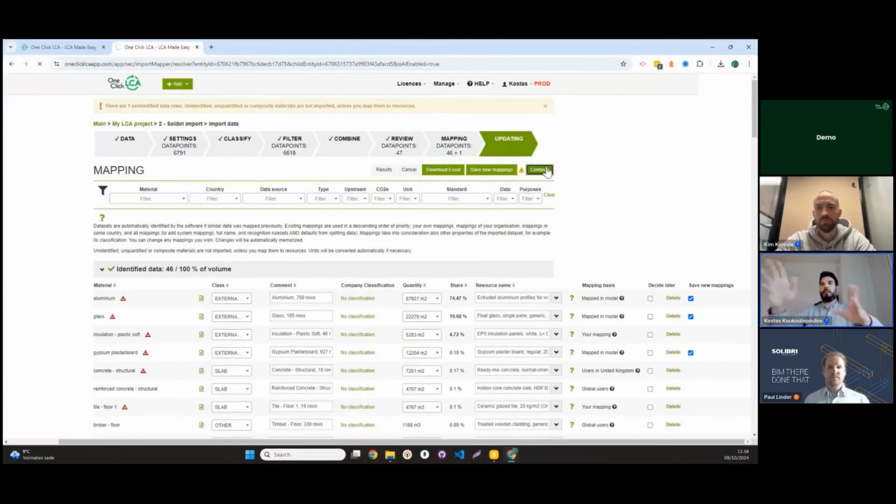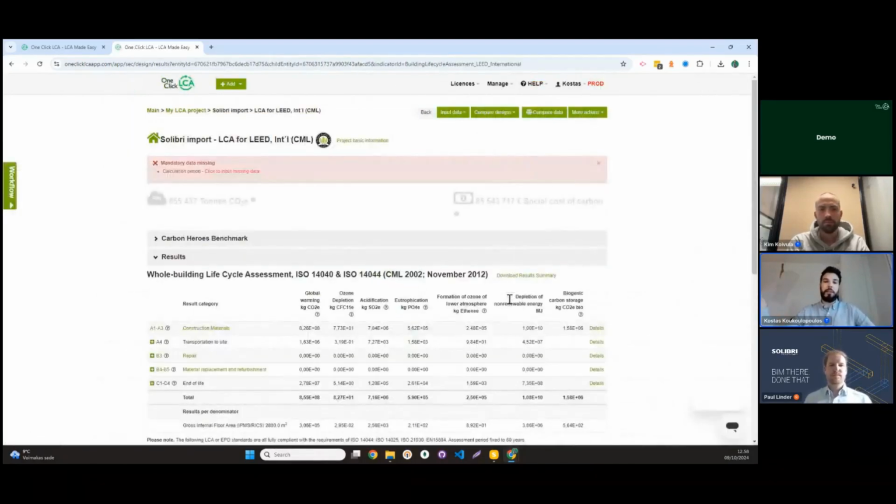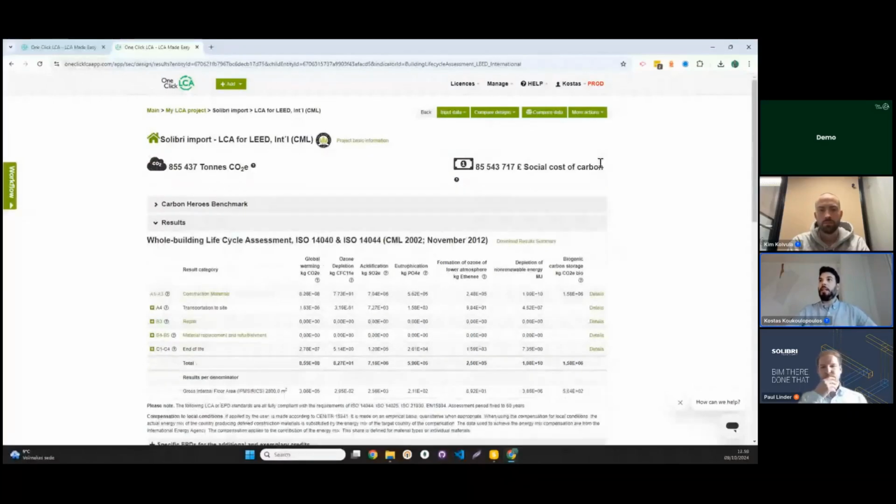So as a next step, I will have done here the environmental profile assignment. You can switch between options and so on. And then at the next step, you get directly to the results. Depending on the certification you are working on, maybe you are just done actually. But for some other certification, you might need to make a few more inputs. And the software is giving you a warning. So for example, in this case, I need to clarify what is the calculation period I'm examining for my life cycle assessment, so that the software can calculate the replacements that are needed for its material.